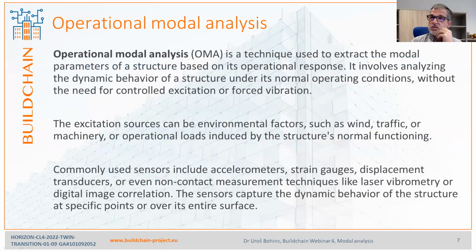So the other class is operational modal analysis, where the excitation is not known, and the excitation normally comes from the environment, and there are various kinds of excitation around, whether it be wind, traffic, some machinery operating nearby a structure, or micro tremors, earthquakes, and so on.